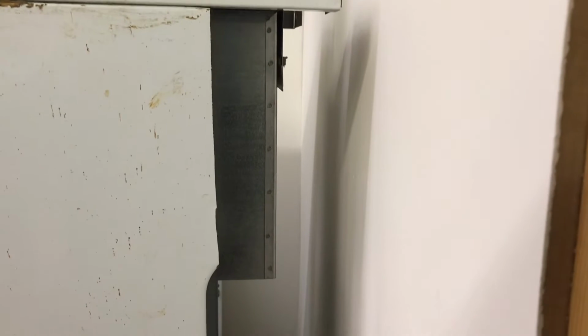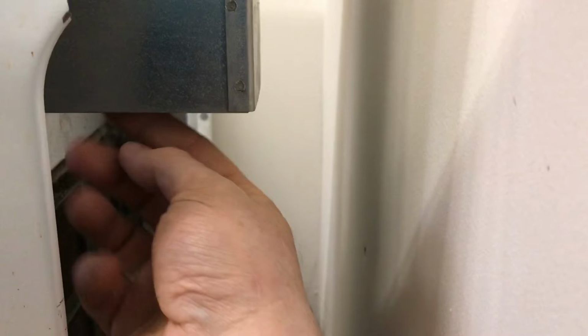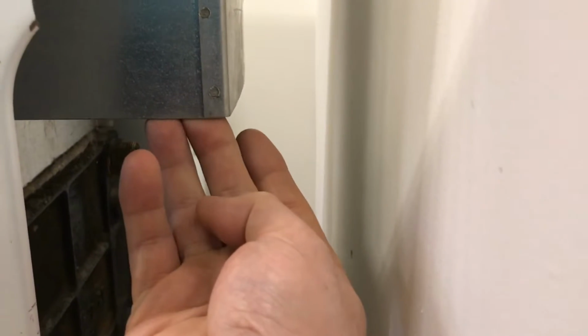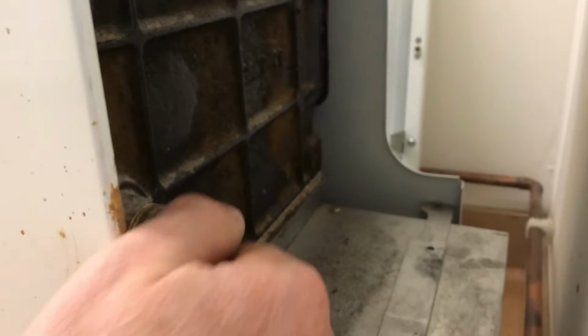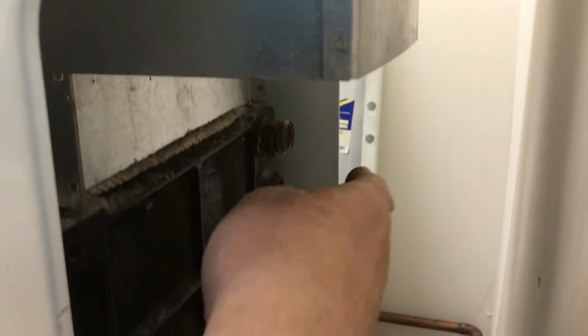Now this part you're seeing of the open flued boiler is the back, and if we zoom in, this bit here is the draft diverter. What would happen here, if we had downdraught from the flue, is the air would come out this way and not affect the boiler itself. At the back you can see the water connections. There's one water connection there, so that's the return. That's the flow pipe, and that's the cast iron heat exchanger. So here is where we would do what's called a flue flow test and spillage test, to see whether any products of combustion were coming back into the room.